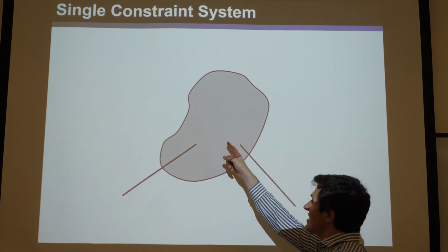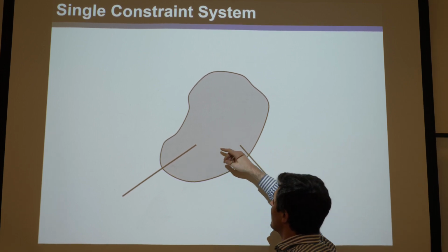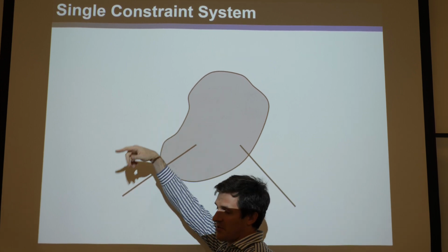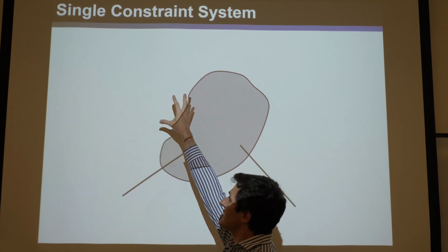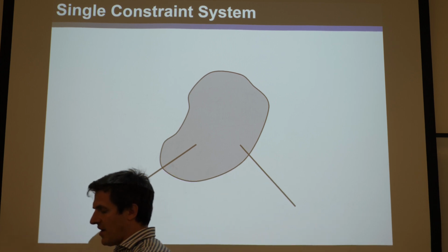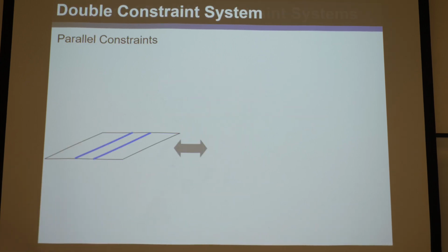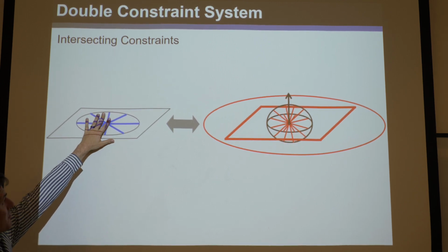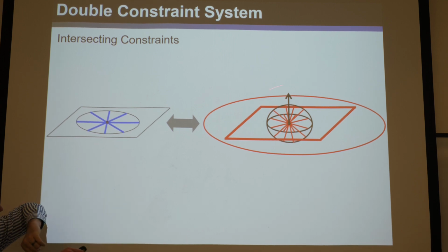Now, it doesn't matter if that disk is inside the potato or not. If these two had been like this here and I move this there, so they intersect somewhere outside the potato, it doesn't matter. The constraint space would still be where they intersect and be defined by the plane, and the freedom space would still be the same thing here. Okay, so it would be there, and it would be defined by the plane of these two, and its freedom space would be locked on top, and that would show how that potato could move. Okay, so the point is, we've just found a second freedom and constraint space type when you have two wires you're sticking in something.